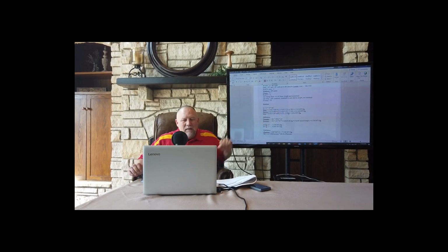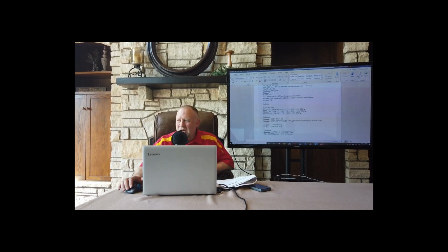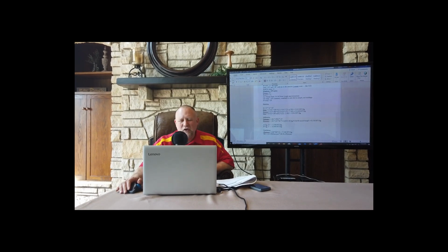It's negative 20 outside. So we multiply those out, and I get 3,312 BTU per hour. In this class, you do not need to go more than 4 significant digits. I do not want to see an answer that's 3,312.4625839 BTU per hour. And the reason is, let's not attribute our answer to a higher level of precision than is possible, and you can't buy equipment that's accurate anyway. All right, so no more than 4 significant digits, please.